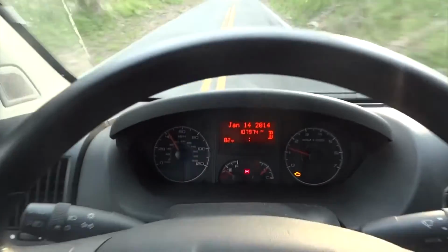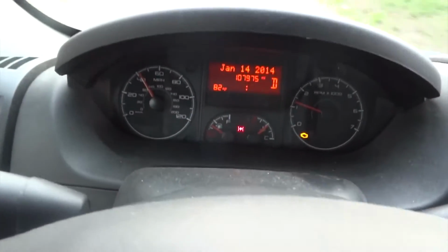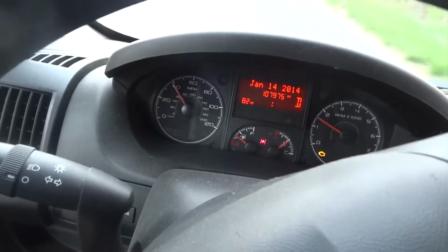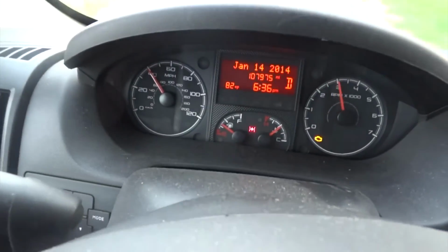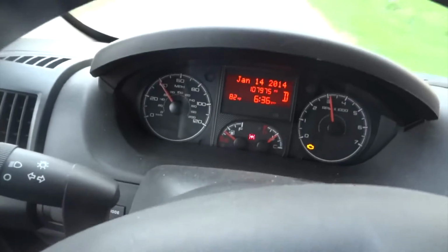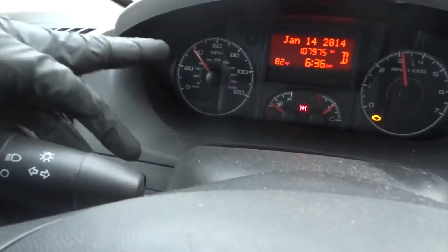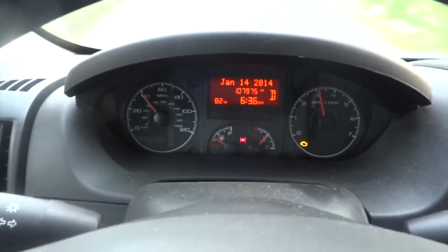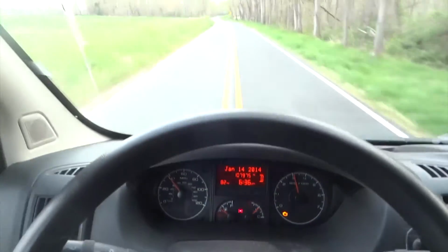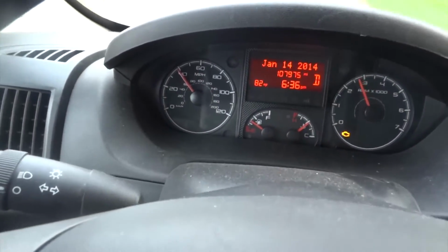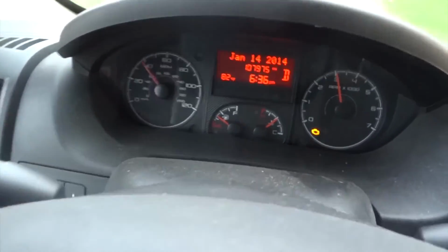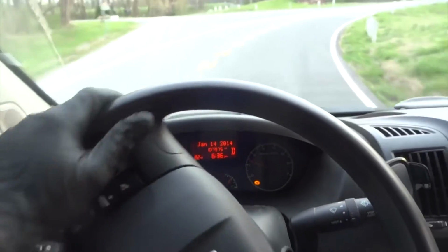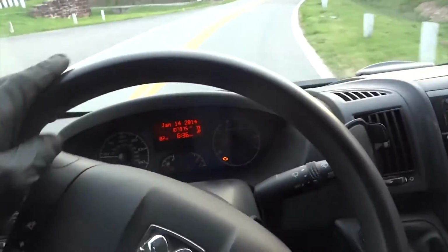As I'm driving, the check engine light came back on and the throttle light started flashing. As you can see, our fault code has reappeared and now the van is losing power. I can't go over 40 miles an hour. We are now losing power. Now we are in limp mode. So now the max speed I'm going is 40 miles an hour. So I'm going to stop here. Let's stop here and look at the scan tool.